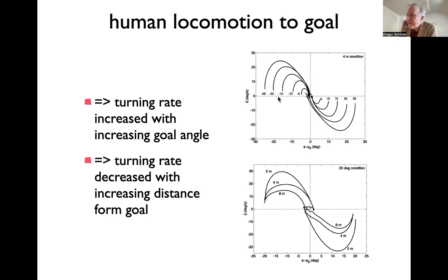Of course, what really happened is that when you're walking after this 1 meter, the obstacle comes in at these different angles. So here it looks like different values, but of course it's the same heading, but the force is just turned on at different moments in time. And so there is some transient where you, in a sense, have to get onto the curve, right? And that's not consistent. That is, at this value of heading, you have different turning rates depending on when this was turned on. And this sort of reflects there is a hidden degree of freedom.